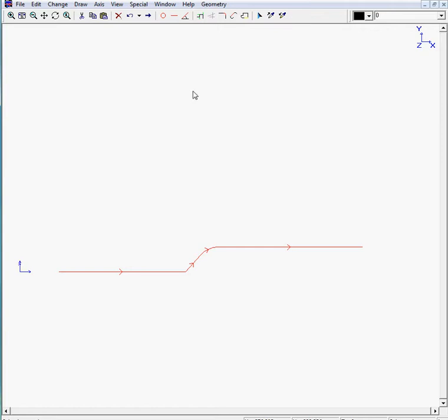And if you take a close look at your drawing, we do not know where this line ends. If you look at the 575 dimension, this does not apply for this line, but a line a little bit higher. So we now need to figure out, as we cannot draw the fillet before we draw the line under an angle, we need to look a little bit further, and we will draw the last horizontal line first.